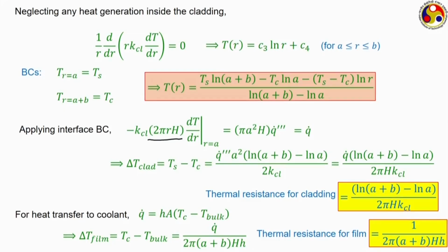to be constant. If we assume them to be constant, then we know how to calculate the 3 thermal resistances, and accordingly we can calculate either the bulk temperature if we know the center line temperature, or the center line temperature if we can calculate or measure the bulk fluid temperature, which is not very difficult. One problem of course will be this small h, the convective heat transfer coefficient, which depends on the properties and also the velocity level of the coolant stream itself. But the 2 geometries that we have discussed here are both quite simple.